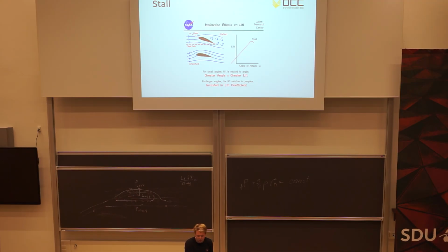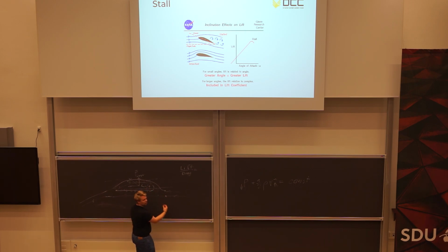Now let's talk a little bit about these things that NASA wants to talk about. If you increase the angle of attack, so the air comes a little bit from beneath, you also have more deflection, and because of Newton, you're going to get more lift. And you get quite a bit more lift. Now you can see that it's almost linear, and at some point you lose it. This is because you get what we call separation.